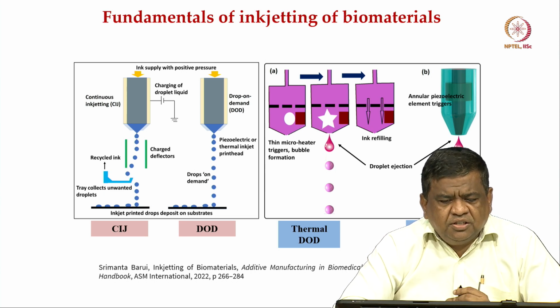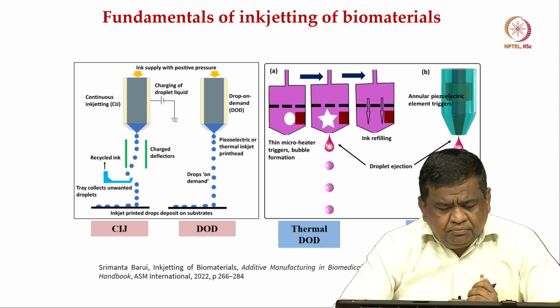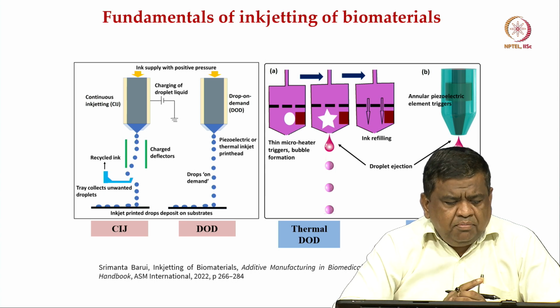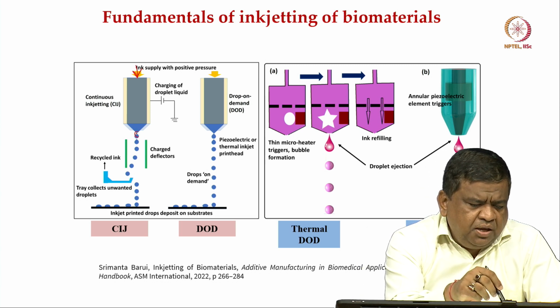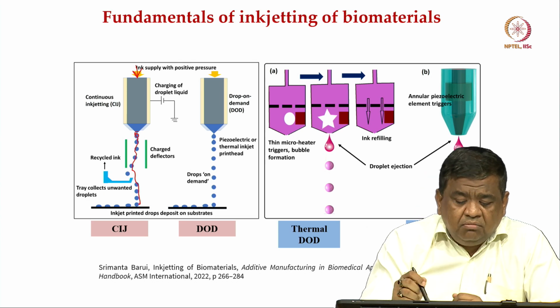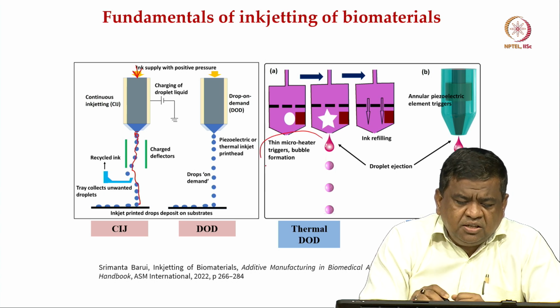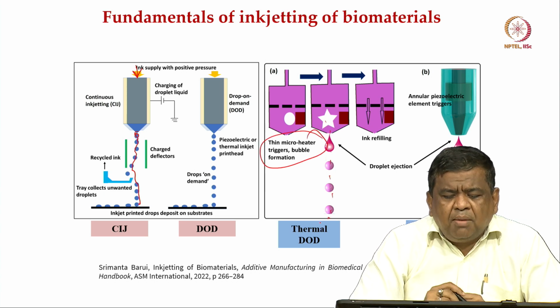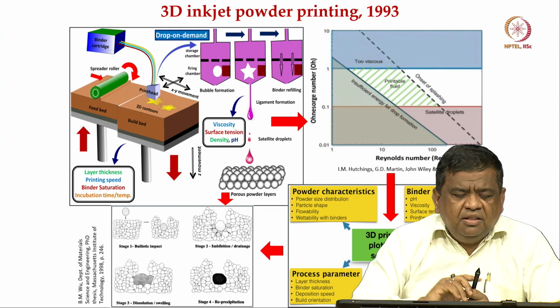3D printing process. This is inkjetting of biomaterials. People use this under different names, like drop on demand. There is an ink supply, and the ink is deposited on the substrate in a drop-on-demand approach. This is a thermal drop on demand, and this is piezoelectric drop on demand. Thermal drop on demand means there are thin microheaters which trigger a bubble to form, and the droplet is ejected. This is shown more clearly in the next slide.